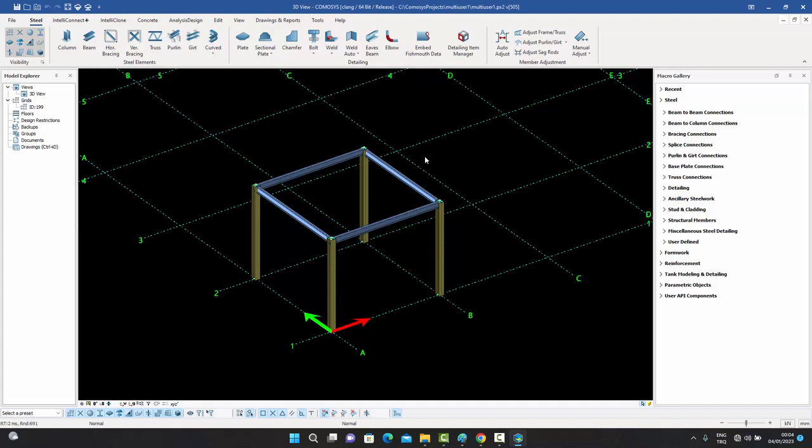This is, of course, a very simplistic example, but typically with large multi-storied buildings, you can divide the building into stories. You can assign story number 1 to user 1, story 2 to user 2, story 3 to user 3, and so on and so forth. And by using this, the whole idea is that you can reduce the man hours, because what can be done in a month, you can do in 10 days with 3 users working on the same model at the same time. This is a very nice technology to have.